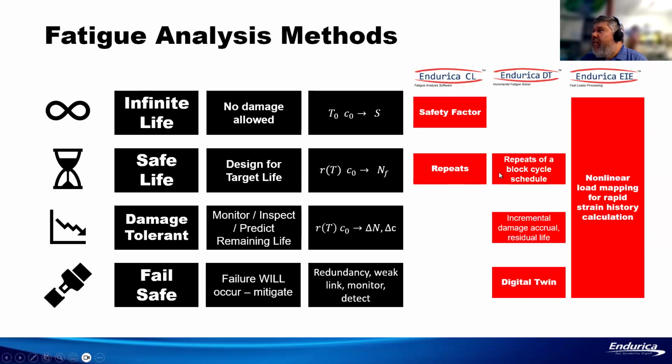That's what we call safe life approach. Now, sometimes in the safe life approach, you're assuming that some particular load case is just repeated to the end of life. But in real life, of course, every day is different. And so that's why we need a damage tolerant approach.